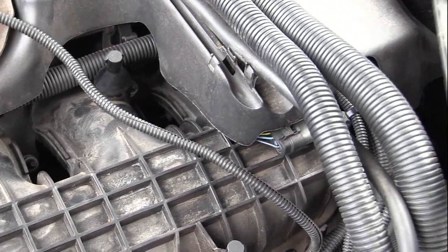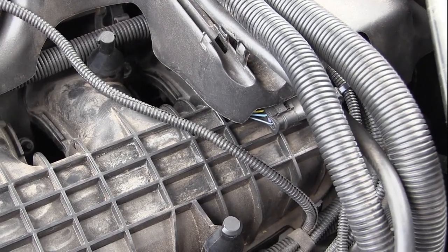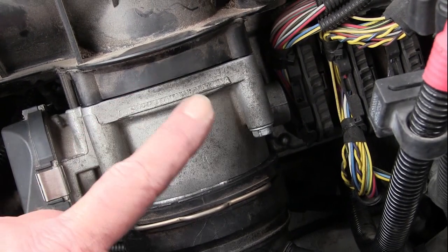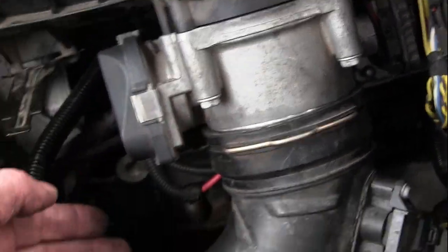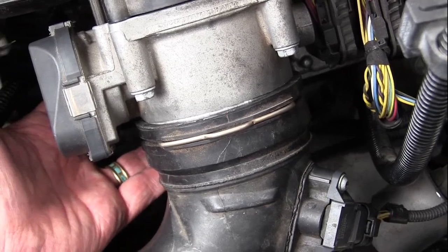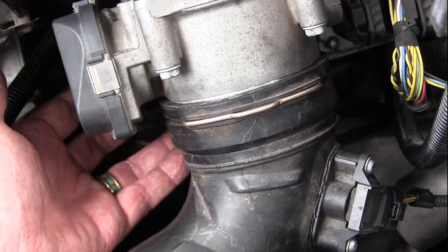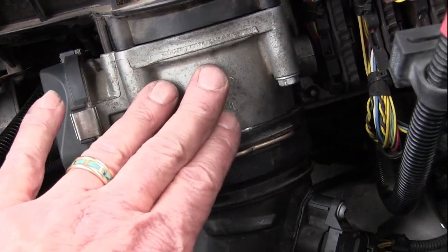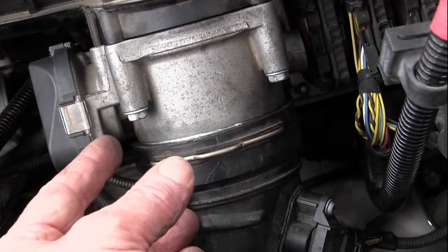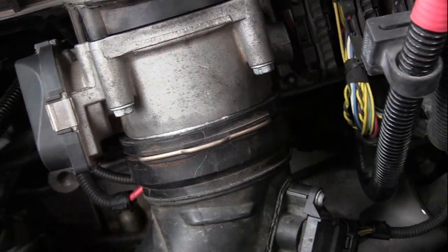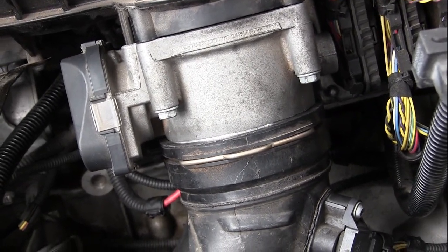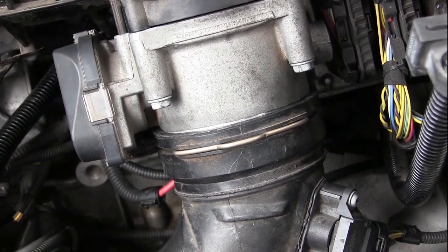Since all the chemical would go to the rear, you would either damage the engine or the cat, and that's unacceptable. The only place that you can put the chemical in is right behind the throttle housing, very close to it. On this N55, underneath here, there's a purge hose and assembly. We're going to take the purge off and we're going to go in there. In order to do this, we need to take the throttle housing off. It comes off very quickly with just these 4 screws. We're going to go ahead and remove that, and then we're going to get our hose on there, and we'll put this housing back on with 2 screws. Let's go ahead and take care of that.